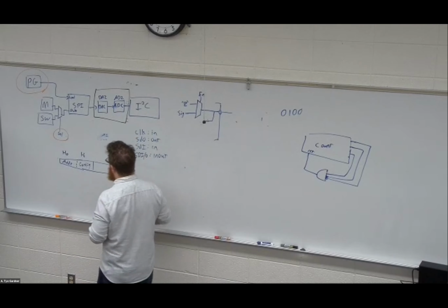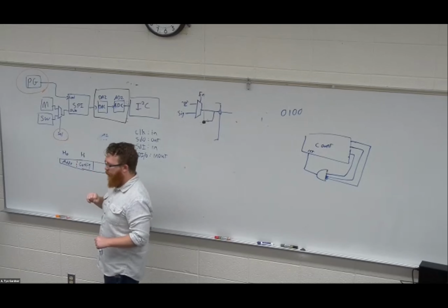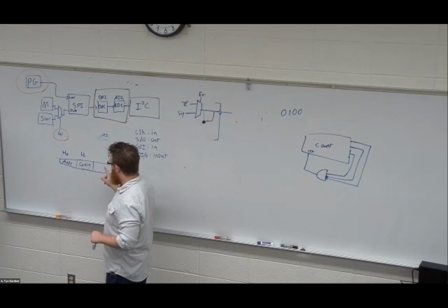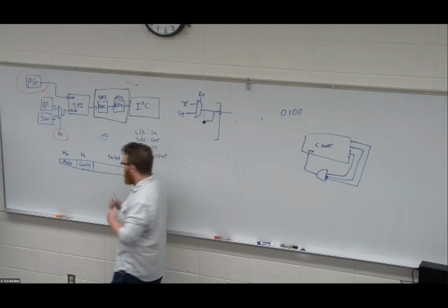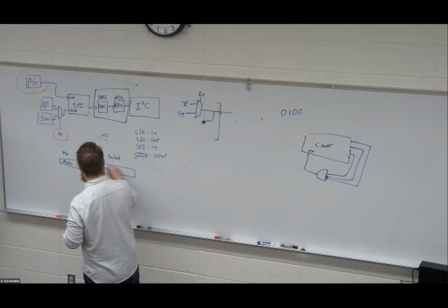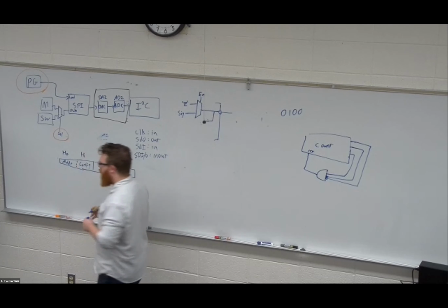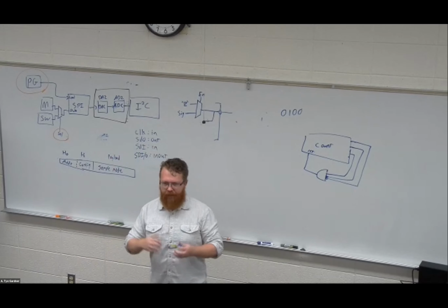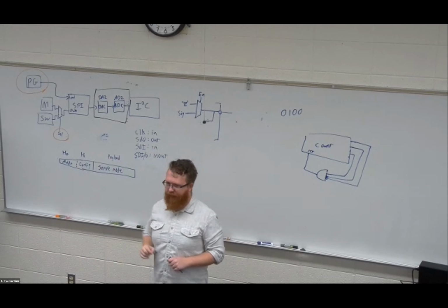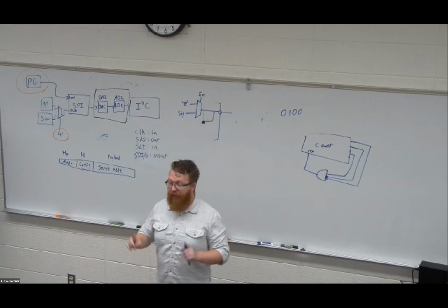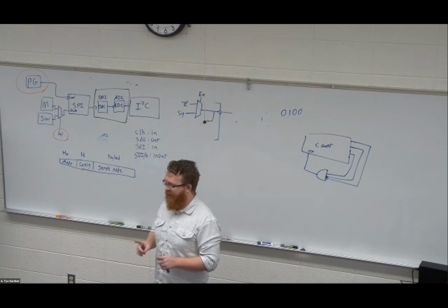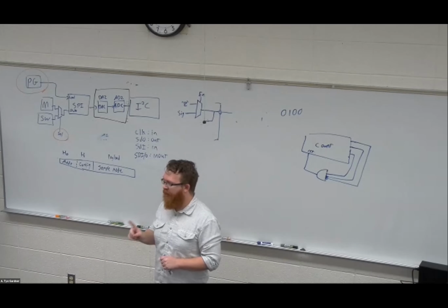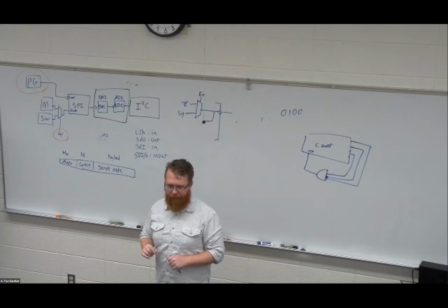So it's going to do something like, say, hey, ADC number 1, I'm going to need a sample from you. This is the sampling mode, for example, is probably what I believe is the payload of this. Because there's multiple sampling methods, okay? One of them is single sample. I want you to send me 1 sample from your ADC. If I need to go faster than that, what I say is, I need you to keep sending me signals, data until I tell you to stop, okay?